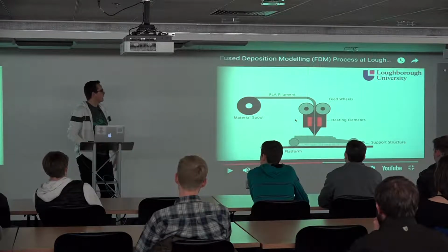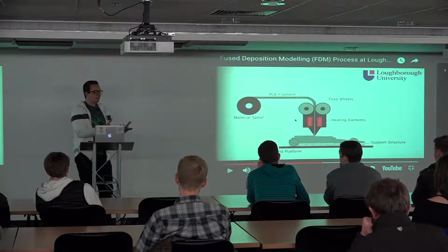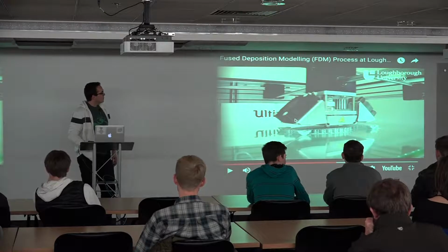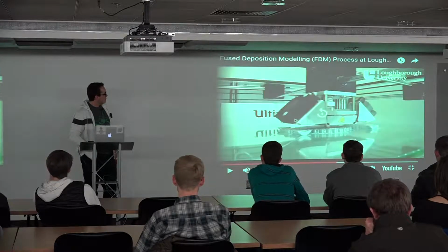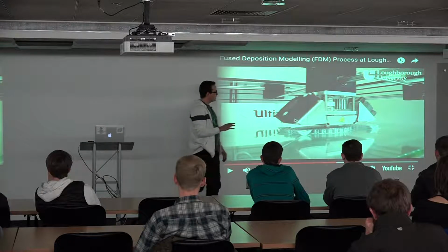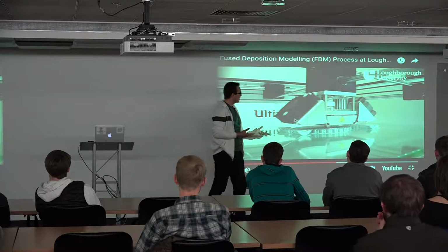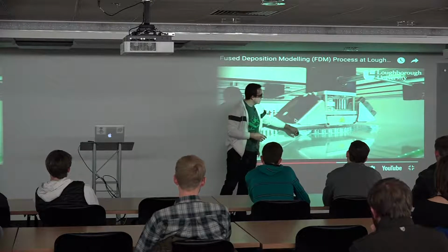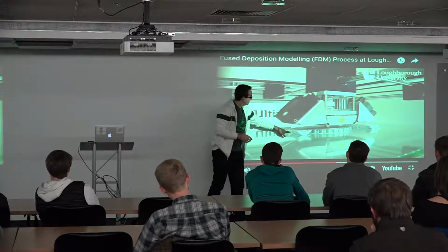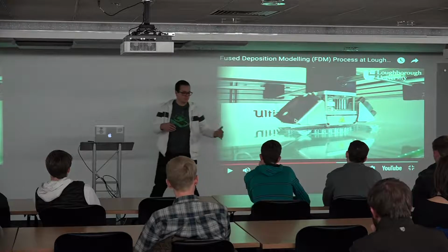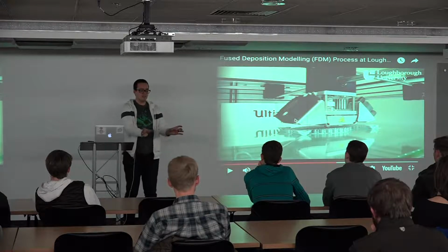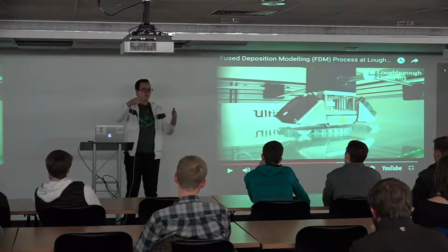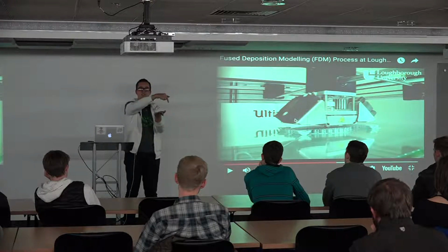and the one that is the most accessible, cheapest, and you get some parts that you can actually use for things. And this is just showing it being built up. And it also highlights one of the other things that's inherent to 3D printing, any kind of 3D printing, but especially this type, is that you're printing up layer by layer. And these little bits here are support material. So if you're printing a bridge and you print the 2 towers of the bridge, layers at a time, then you get up to this layer where it's time to kind of connect across the towers.